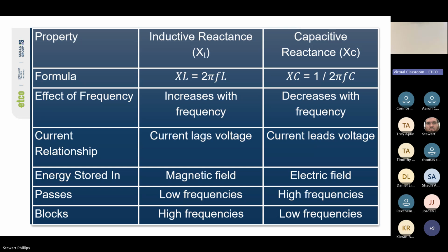Okay, so it gets into the power factor of things, and we will talk about it in more detail in a few lessons. But basically, when we have a leading or lagging power factor, we have more current flow than what we're actually using to do the work. So we're losing some energy to creating that magnetic field or the charging and discharging of the capacitor. So we're losing energy to do the work. A lot of people refer to it as the process of doing business.